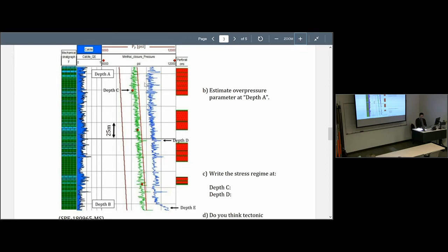In this particular location, because of the presence of stiff layers that usually are rich in carbonates, the stress regime varies from strike slip to reverse. And we're going to see later on that that's very important for hydraulic fracturing, because that makes your fracture go from vertical to horizontal.